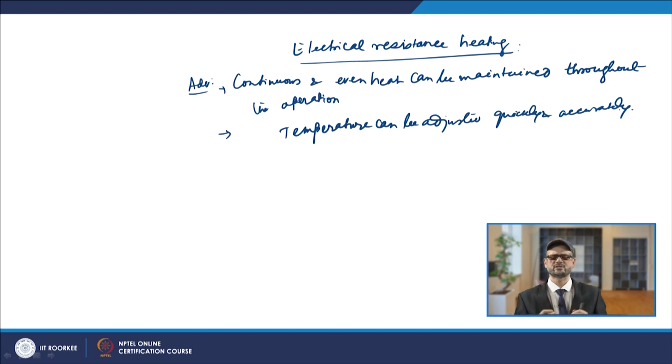In the case of electrical resistance heating, the welders will be at relatively more comfort, because mostly many things work by pressing buttons. They do not have to stop things, because by using the machine itself, they can control the preheat temperature, and increase or decrease it.